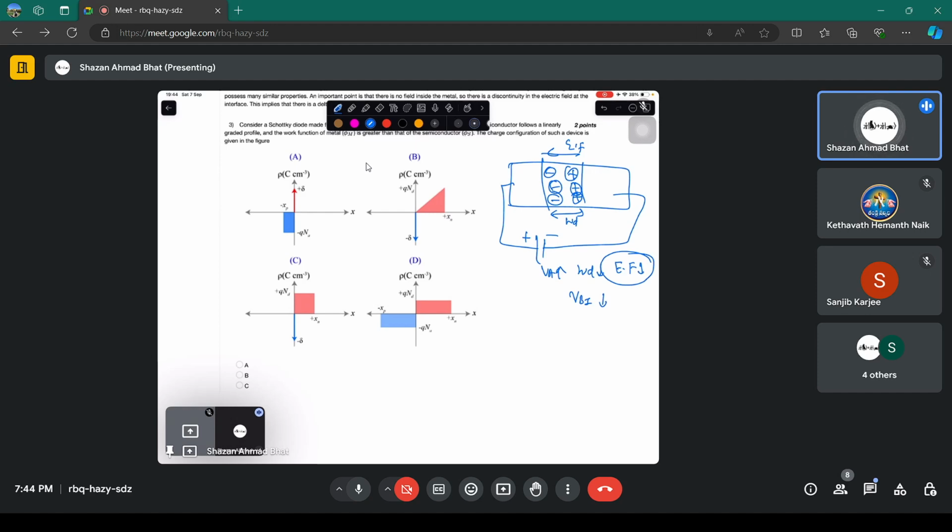That exponential itself tells us that if you apply just a little bit more voltage, the current will shoot up so much that the diode is going to heat up and burn. So that's why you never operate in that regime. If you want to totally make the built-in voltage, or built-in electric field, zero, you have to destroy the diode. So this is the scenario which you can think.